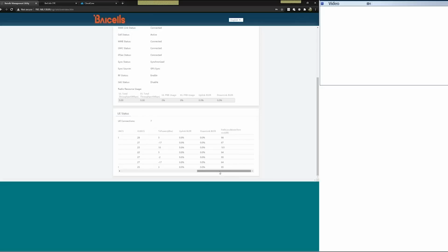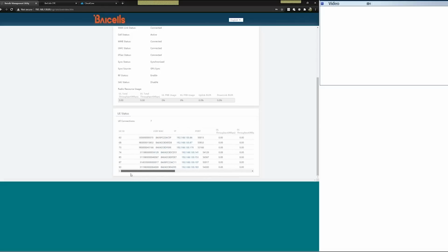But one thing that is difficult to monitor is that because the TX power is always going up and down due to the LTE spec, the uplink MCS will also fluctuate because of that. So if you're trying to monitor, it's a little more difficult, right? If you're trying to track the history of the uplink MCSs assigned, they will move a lot, and that's the unfortunate nature of the way LTE works.